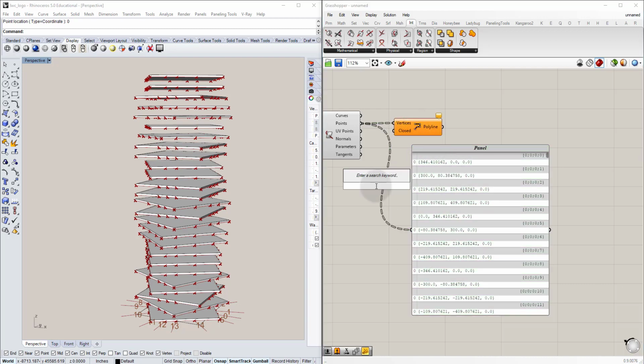One way to do that is using the trim tree component. And what it does is it trims it one layer down, the branches. So instead of being 0, 0, 0, 0, it's going to take it one level down. Each time it takes a level down, it reduces the structure of this tree. And we'll see what that looks like.